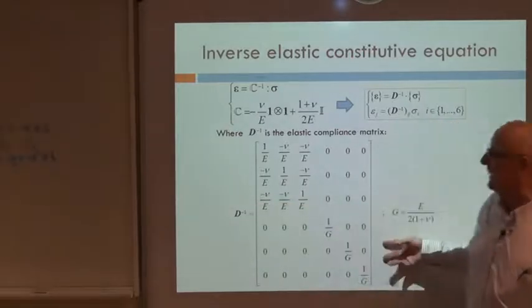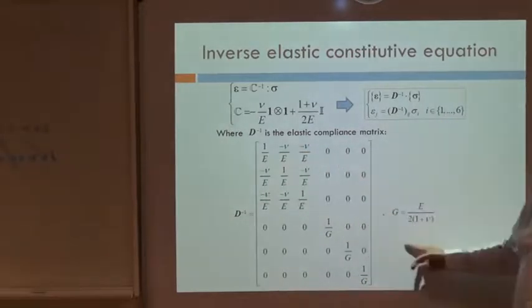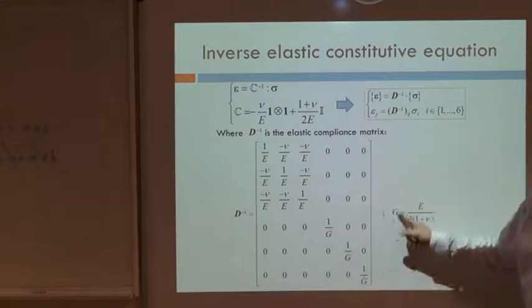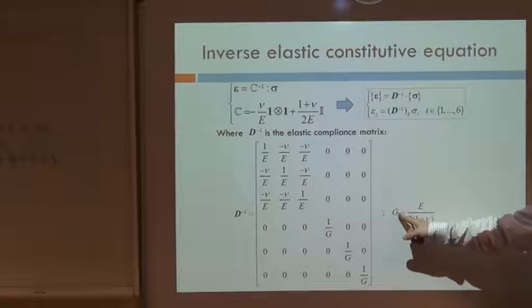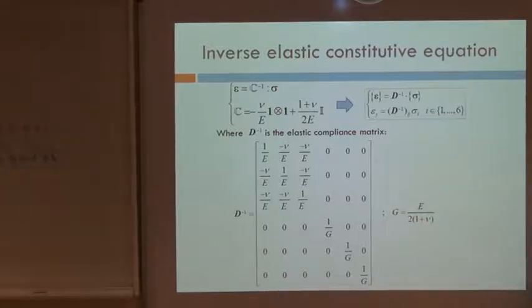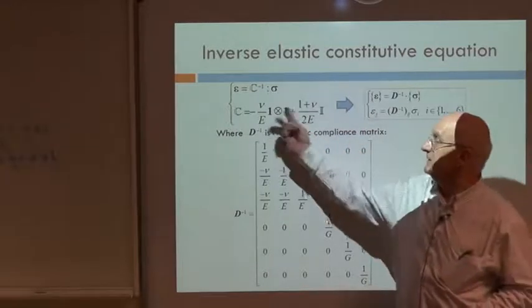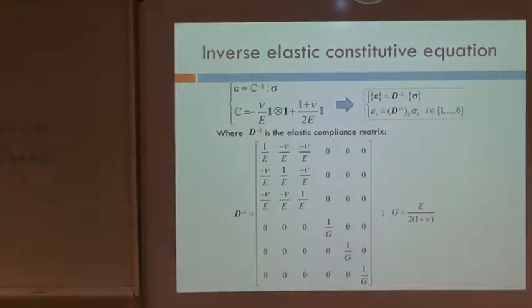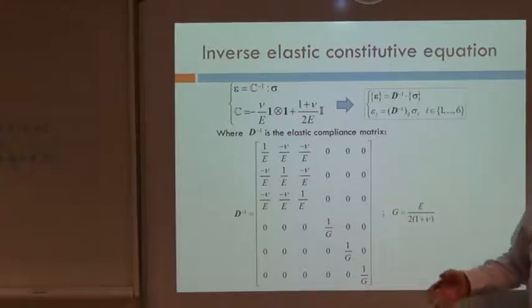And it can be computed in that way, in terms of E and mu. That's it. And G, do you recognize this one? The shear modulus. Oh, okay. Is this the matrix characterized for a specific type of problem, like plane stress? No, the general 3D. Of course, it's isotropic elastic, so there are only two parameters, mu and E. You have to characterize, or whatever you can. Two parameters only. Okay. So now, the algorithm.